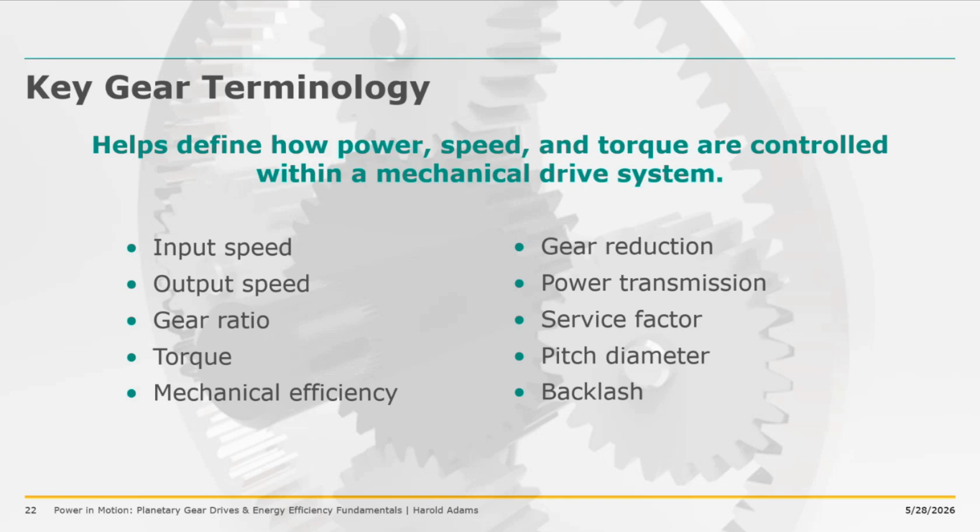And for our fourth key terminology here is torque. Torque is the rotational force produced by the motor and transmitted through the gear system, measured in pounds-foot or Newton meters. As speed decreases through gearing, torque increases.